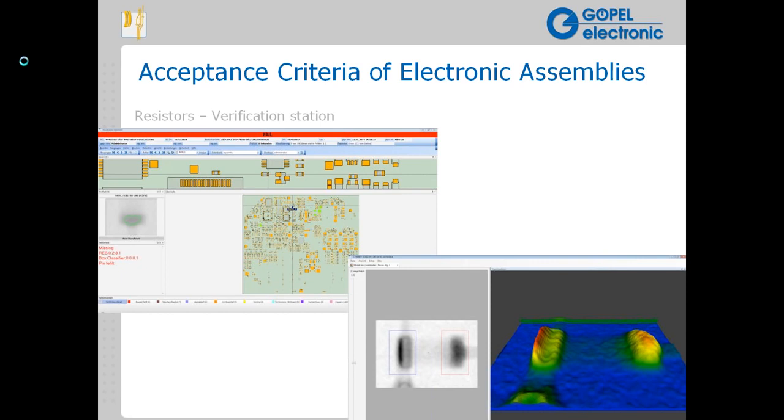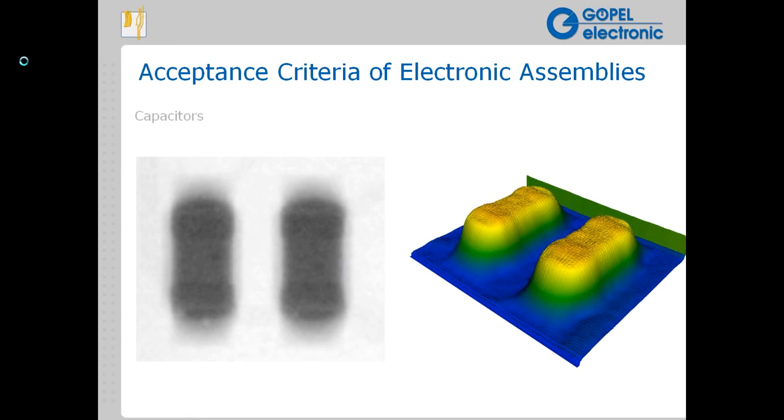When setting up a program, the software allows us to profile what a capacitor should look like. And again, I should point out here that this is all library driven. One of the aspects of the software setup and programming in the Xline 3D system is that the software is driven very effectively by a very robust library of components. And the nature of these components is defined, and with respect to capacitors, the nature of the device, the package, and the solder joint is defined, which helps us to produce proper detection for these kinds of components.